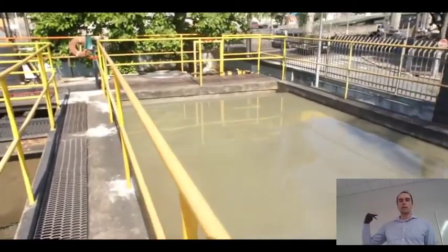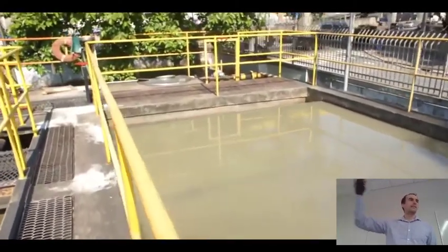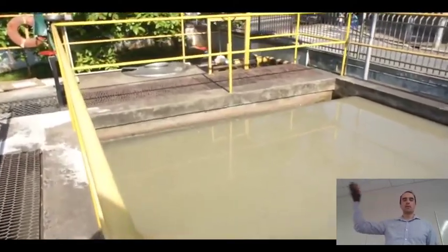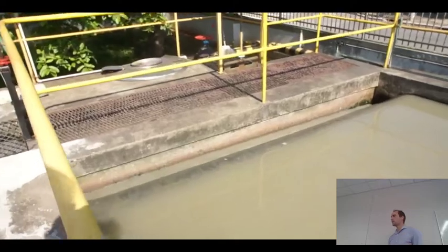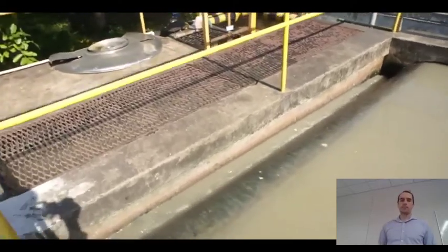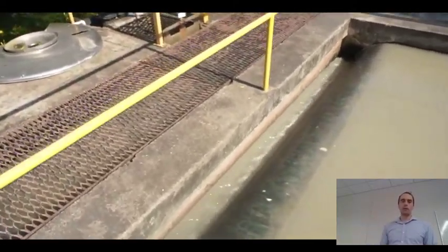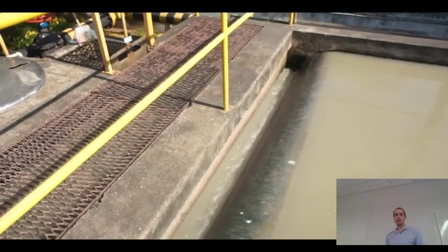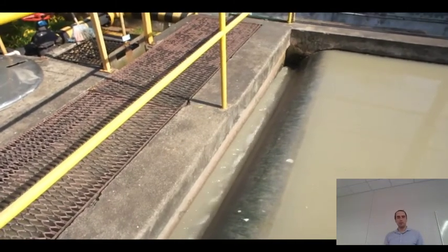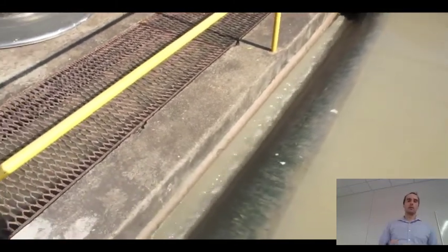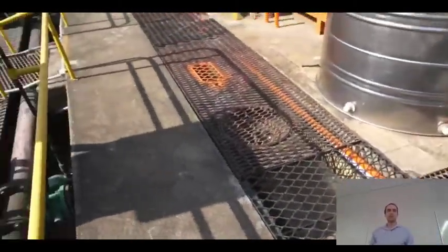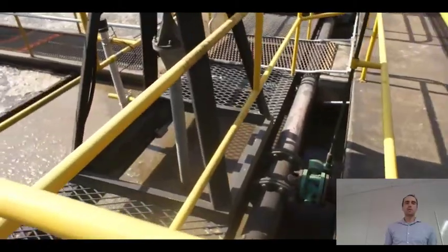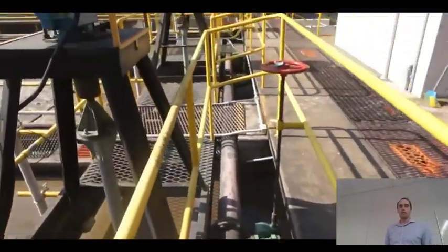So water is just making its way through. It's quiescent, laminar flow. They're harvesting water across the top. Sludge will accumulate along the bottom, and they'll take that away over time. So you see it's spilling over that top. So that's probably the primary effluent there we're looking at. It's going to head over into the secondary treatment step. And you see it's pretty nasty looking. So then it makes its way over to here.